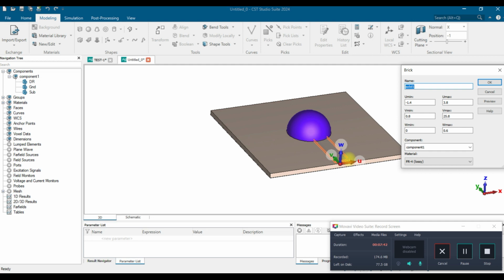Okay, so this one is the feed, and its position will be minus 3.7 divided by 2 plus 3.7 divided by 2. This is not the perfectly optimized width of the feed, so you can optimize it to get a better return loss also. And this is V0 to 23, which I optimized a little bit previously, that's why I took that value.